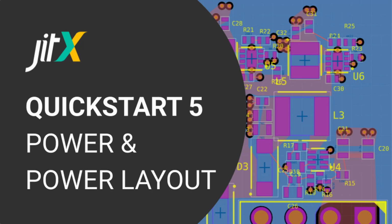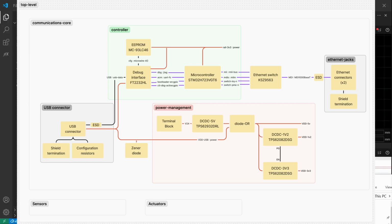In this video, we'll get back to coding our design, adding the power management circuits that translate 24 volts in to the 5 volt, 3.3 volt, and 1.2 volt rails. We'll practice the skills of pulling in code from libraries and wiring circuits using ports, using parametric functions that automate detailed regulator design, and we'll also go through the automated layout tools for creating power geometry and optimizing power layouts.